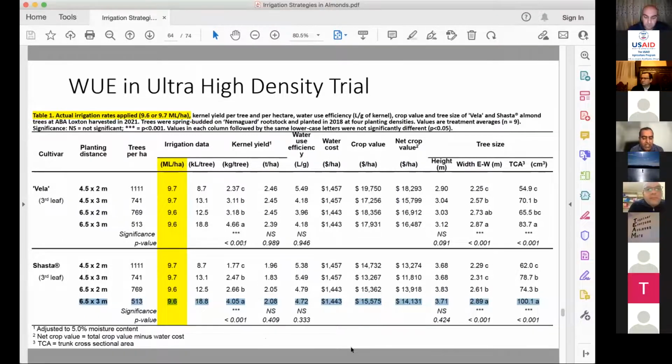A pH of 8 and beyond, I mentioned that if you irrigate your orchard with water of that high pH, eventually your soil is going to become like that in the root zone, unless you do some soil amendments or irrigation water treatment. So if you have high pH, we recommend some soil amendments, or we recommend treating irrigation water with some acidic amendments.